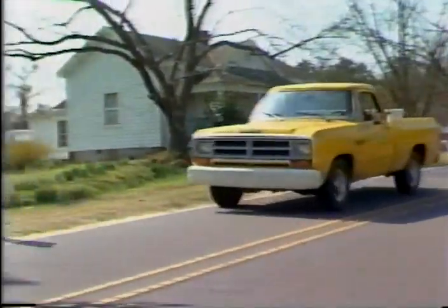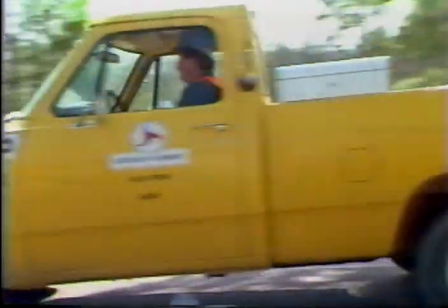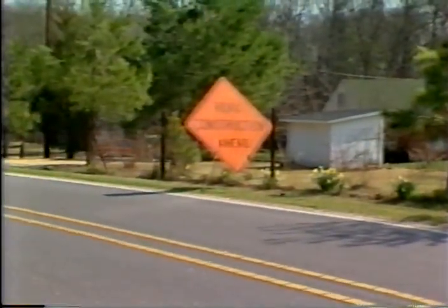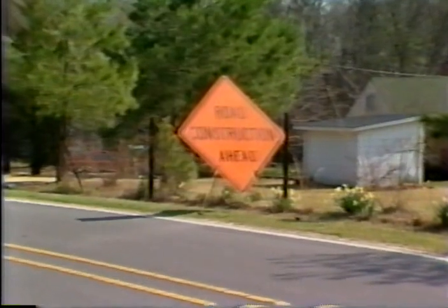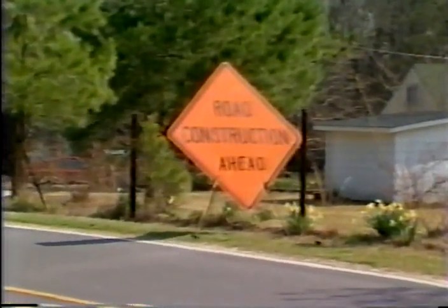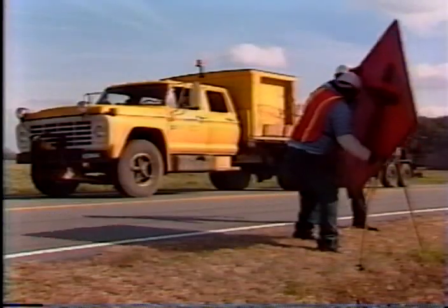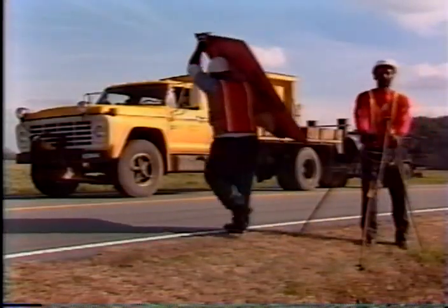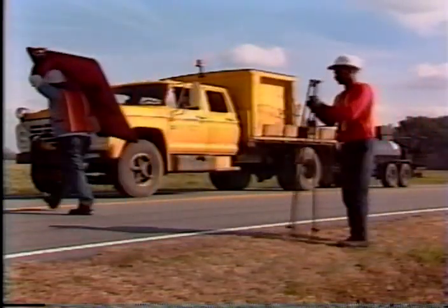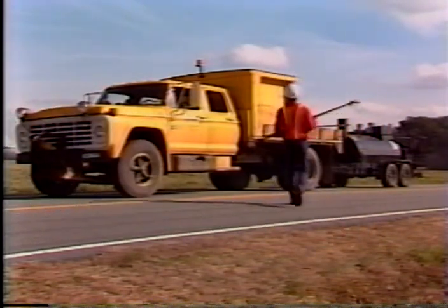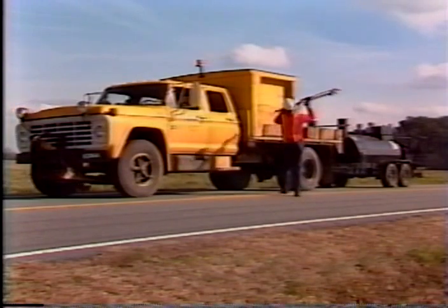The crew supervisor is responsible for seeing that the traffic signs and flagmen are properly located. Periodically throughout the operation, check the traffic control devices to be sure they are still visible. When the maintenance operation is completed and the traffic control devices are no longer needed, remove them immediately. Remove the signs in reverse order of placement.